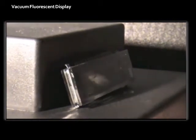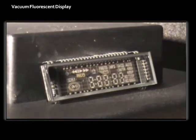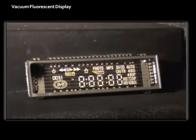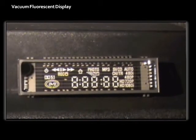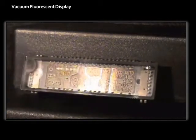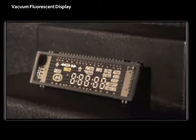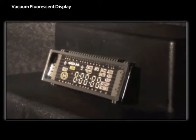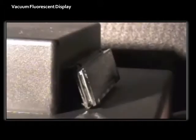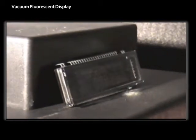VFDs are used in applications including automotive, industrial, appliances, and audio-video. Vacuum fluorescent displays can be made as just the glass with pins, or as a full module. As just glass, the filament AC voltage and the grid and segment DC voltages must be applied. As a module, the filament AC voltage is generated onboard, and the built-in controller receives parallel or serial instructions and displays the desired characters. A color filter is then applied to the front of the display to change the traffic light green color to nearly any desired color.